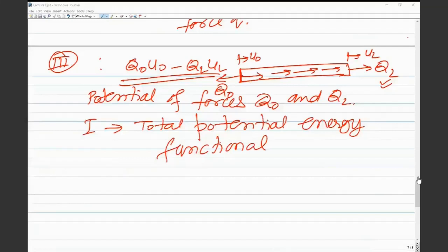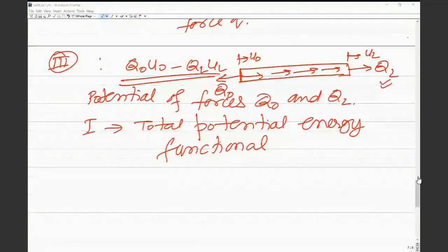The other boundary condition is in terms of the second set of primary and secondary variables. The second boundary condition is that the bending moment is 0, but the corresponding primary variable, dV by dx, is not specified. That is an unknown at that boundary. So again, you see the same thing: either the primary variable is specified or the corresponding secondary variable is specified. Okay, sir.